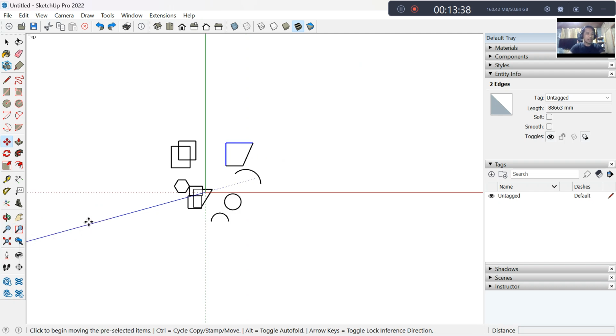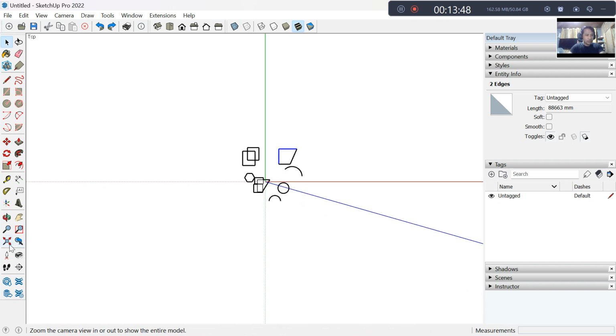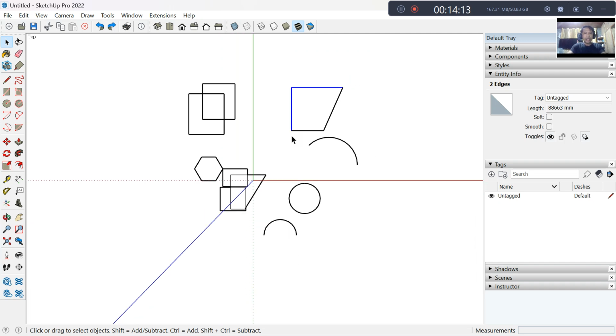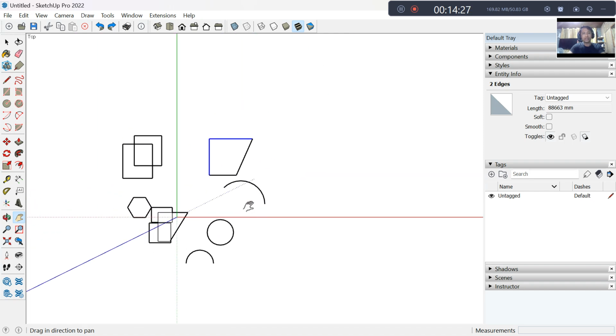You can also use the zoom window here. Click here, then zoom. You can also use the zoom extents here to extend the drawn objects onto the limits of the drawing area. Click the zoom extents and automatically the object is zoomed out into the limits of the drawing area. We can also use pan to move the drawing area using the hand-like tool here. You click that and then you can move the drawing area.